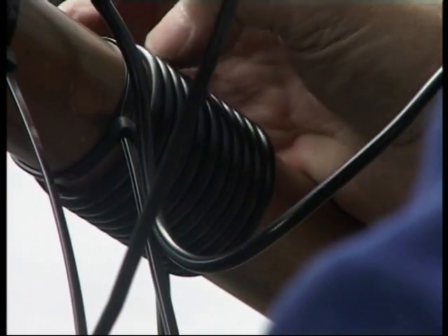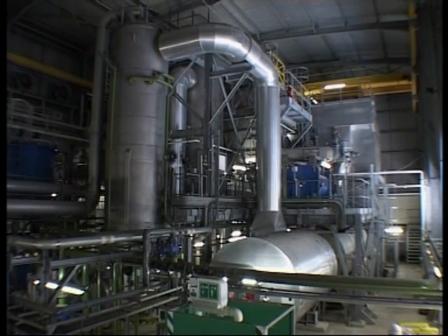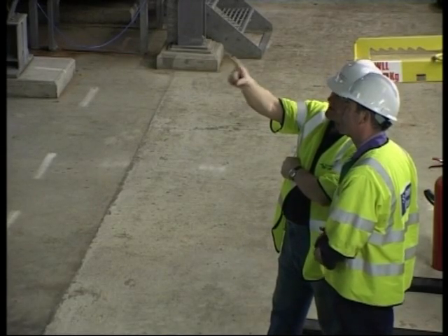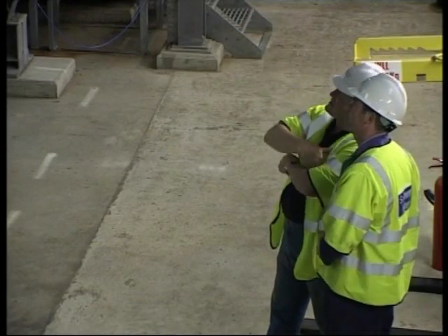Physical conditioning is very versatile because it can be used before any domestic water treatment product, a boiler, a shower, that type of thing. And so you can protect a dedicated piece of equipment to prevent scale formation, or it can be used for whole house protection, and that can be very effective. And at the commercial level, where you've got engineers monitoring the effectiveness of the devices, then it can be very effective in maintaining heat efficiency, energy efficiency in circulating systems.